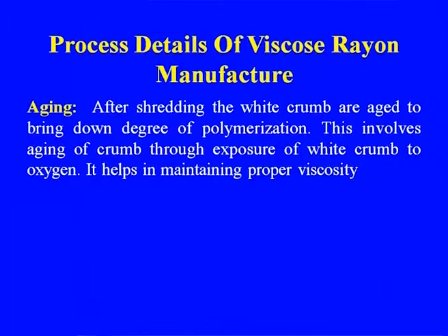Then comes the aging. After shredding, the white crumb is aged to bring down the degree of polymerization. This involves aging of the crumb through exposure of the white crumb to oxygen. It helps in maintaining the proper viscosity. This is the next step after your shredding.